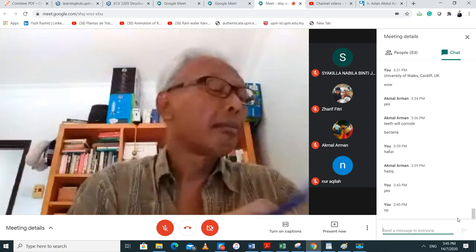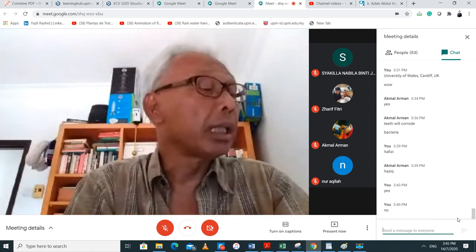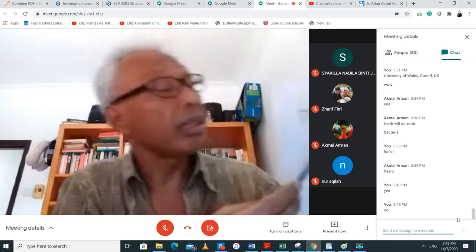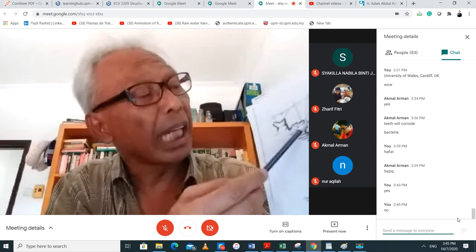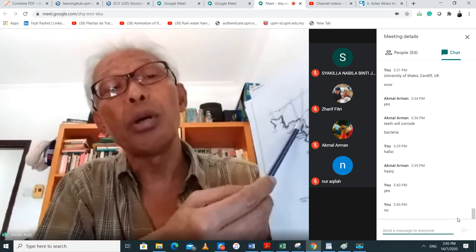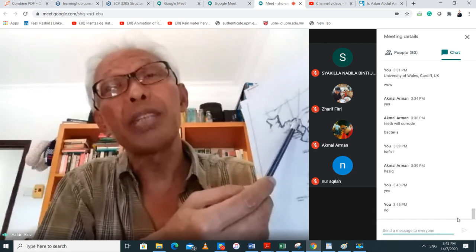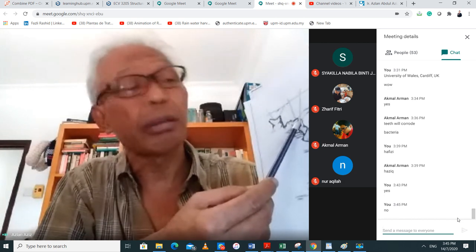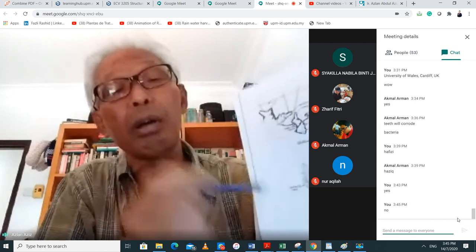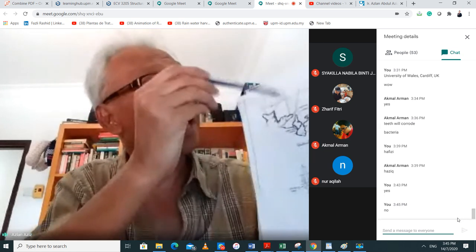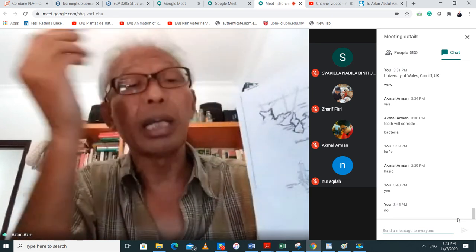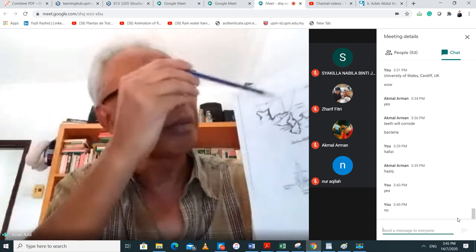Okay. So then on that overhang, like I said, you have cracks there. See, I have a crack there, and you keep banging on it because you're thinking again that you're going to have your pile supported by a rock type of material. And what happens if you keep banging, there is a crack there, and then it will just fall off one day. Because soon you are applying load to this pile. You're going to have your column load, and then you're transferring all that column load to that pile, no?